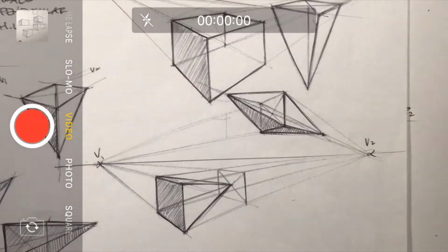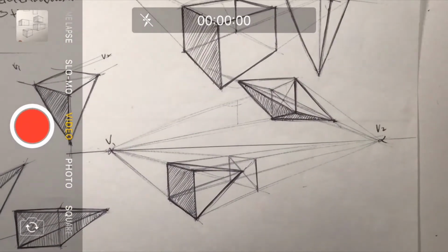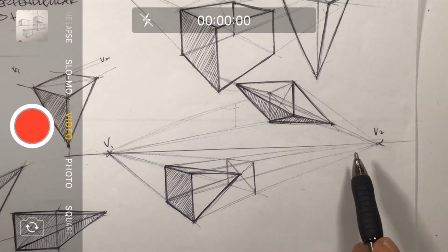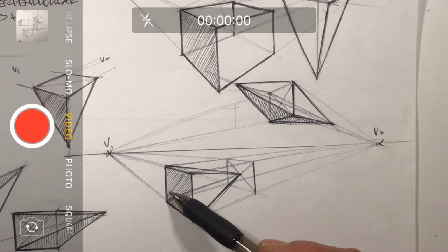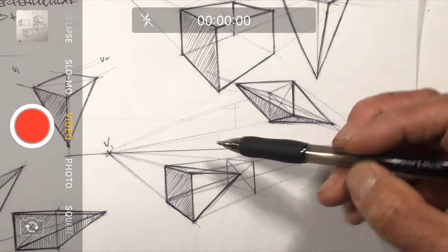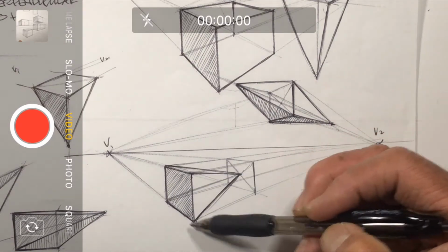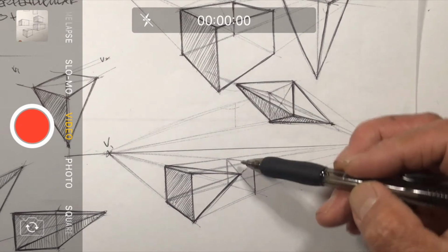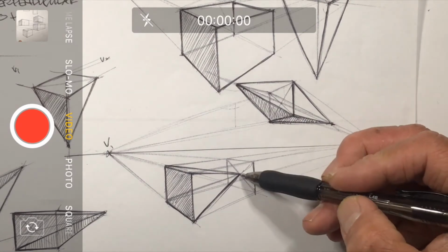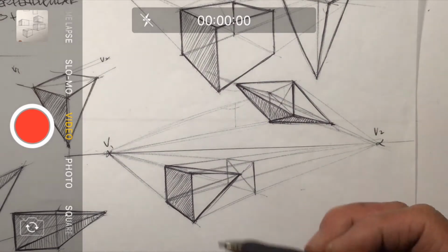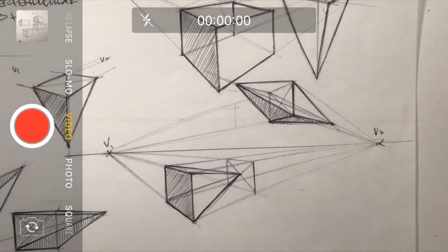Pyramids drawn on their side, like these two images here, you can see I've constructed a 2-point perspective box below the horizon line. The end faces are proportioned to be squares. I chose to have this left vertical face as the base of my pyramid, and to find the point, of course, crossing those diagonals gave me the midpoint of that square, and then you can finish off the construction of that pyramid tilted on its side.